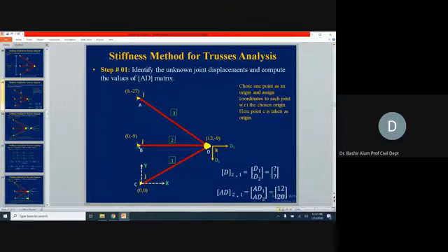Now again, joint J, horizontally it is at the same location, so it has horizontal coordinate 0. But vertical, if you remember, this distance was 9. So we are putting minus 9. Why minus 9? Because downward is our positive direction, but we are going against that downward direction. We are going in the upward direction. So it means this is minus 9.